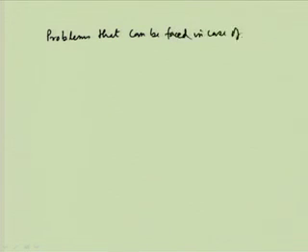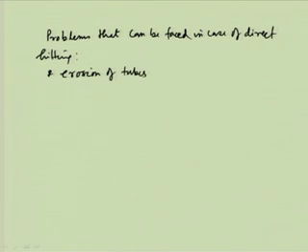The problems that can be faced in case of direct heating are erosion of tubes, then cavitation due to buckling of tube bundles.